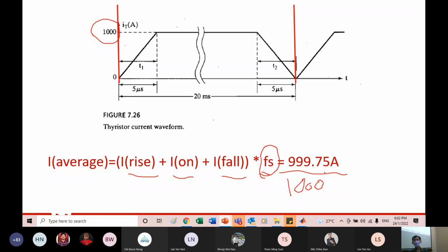That's why you see our adapters getting smaller and smaller, but power higher and higher. That is because they use high frequency. Of course, we also notice that it's getting hotter and hotter. But like I say, not an issue. As long as you know how to do a proper thermal heatsink design, things still can be solved.